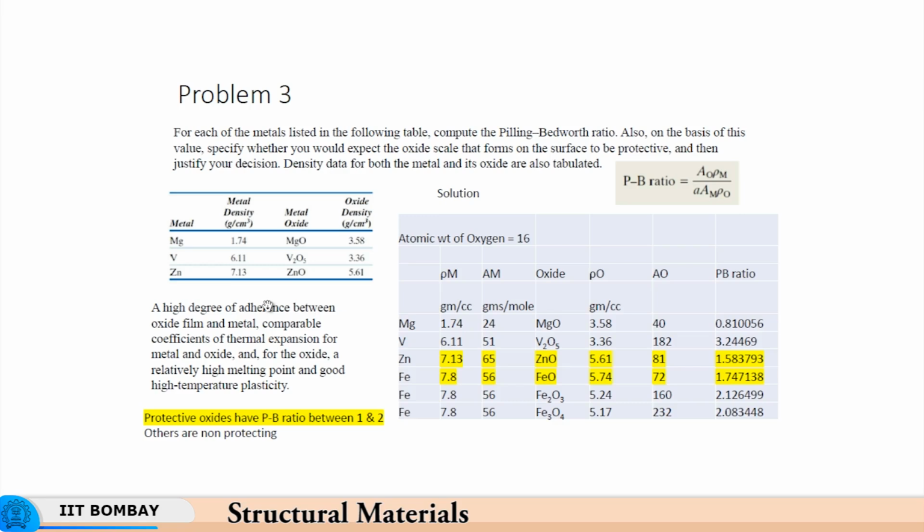In fact, there is a process called bluing, that is, this oxide FeO appears blue. If you give this treatment to, let us say, tool steel, it makes a relatively wear resistant oxide on the surface which is adherent to the surface, and which also increases the life of the tool by decreasing the frictional coefficient between the workpiece and the tool. So, many tools are given this treatment. So, this oxide is a protective oxide, right.